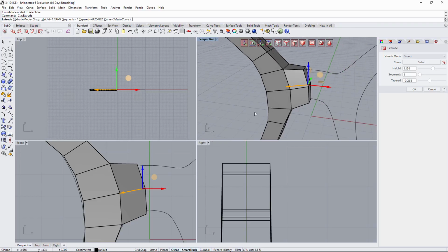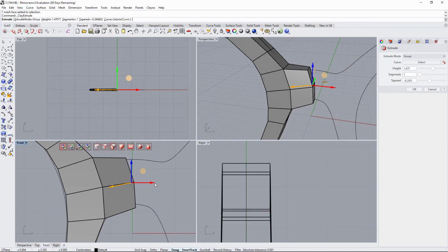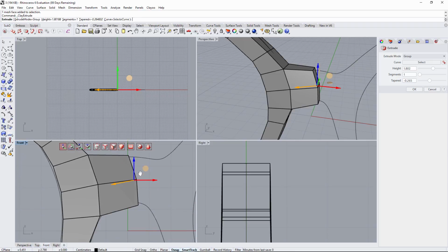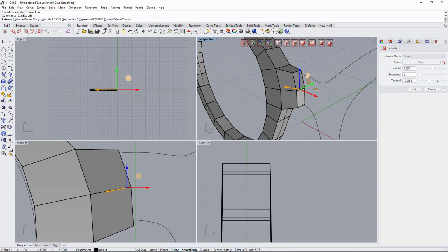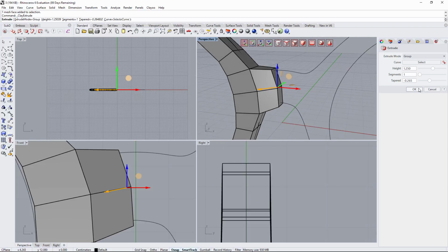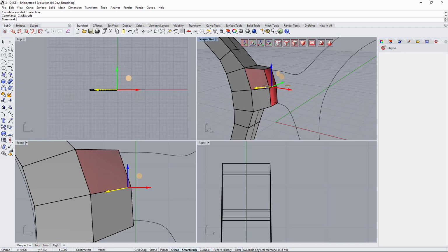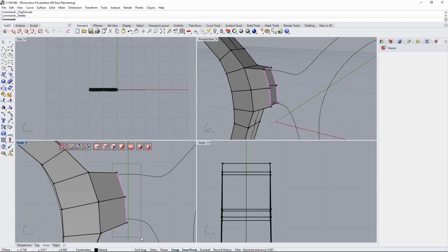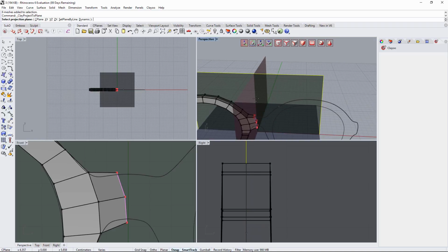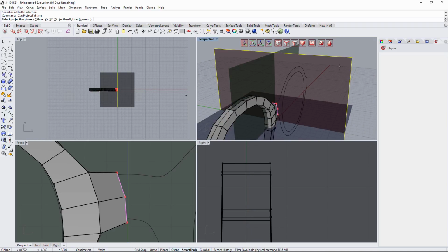Somewhere like here. Be careful not to trespass the z-axis here. Just keep it a bit before it, here maybe, and we will taper it a little less, something like this will work, and validate the extrusion, and then delete the new faces because we want to use the naked points here to be projected on the white Z-plane here.